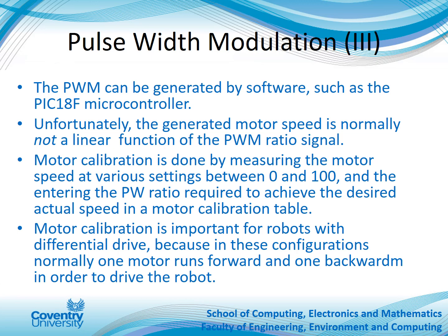Microcontrollers like the M68332 have special modes and output ports to support PWM operations as well. The digital output port of the PWM signal can then be connected to the speed pin of a power amplifier, such as the ones that we've shown previously. Further on, you can vary the speed via the PWM settings over that speed pin.